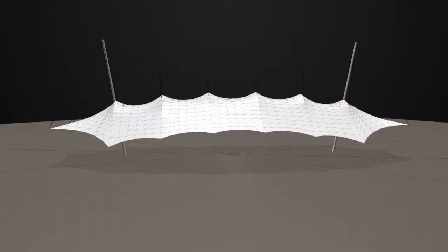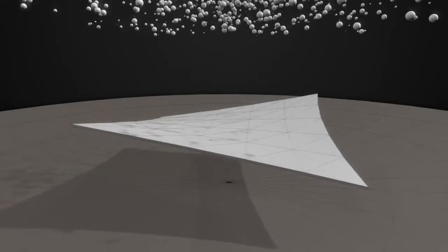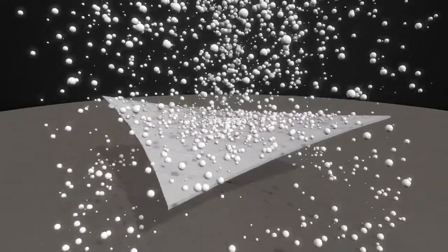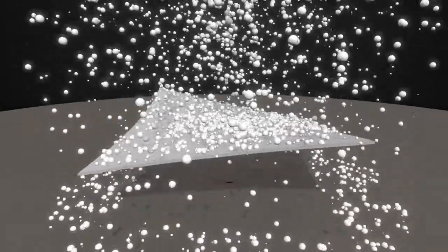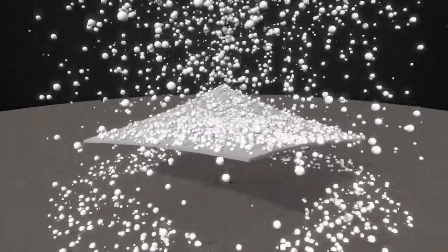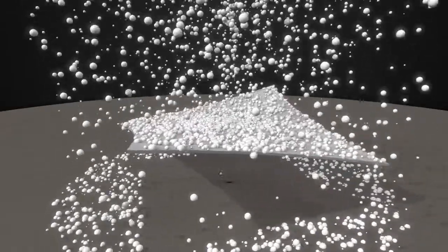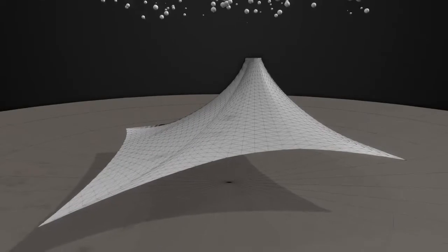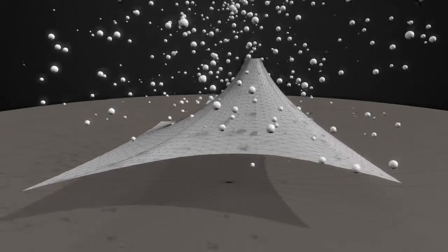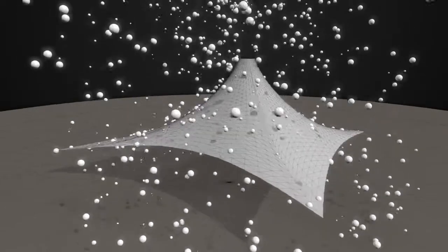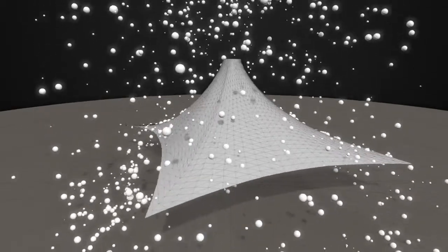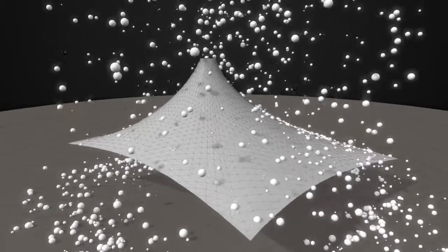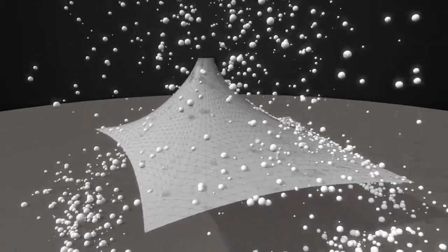In many situations, consideration for the load that snow will impose on a structure is equally as important as considering its ability to withstand strong winds. With the added risk of snowdrifts, we have to be mindful that this can lead to water ponding. For areas where heavy snow load can be expected, structures are generally designed to have smaller spans and a greater degree of inclination to encourage the snow to slide off. When designed appropriately, fabric structures can withstand the most extreme weather conditions.